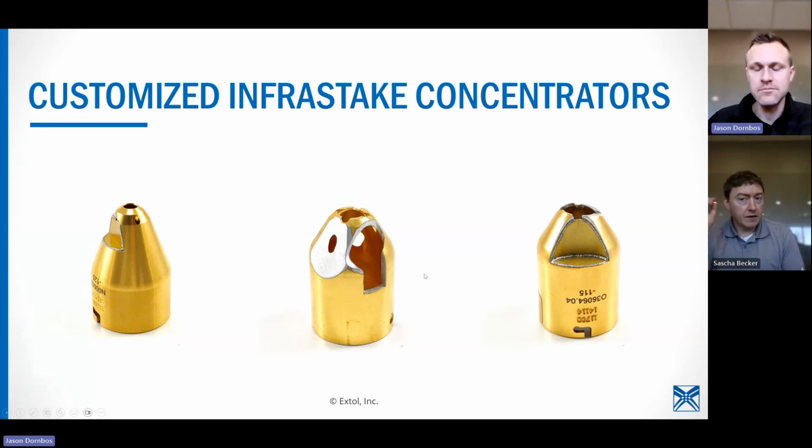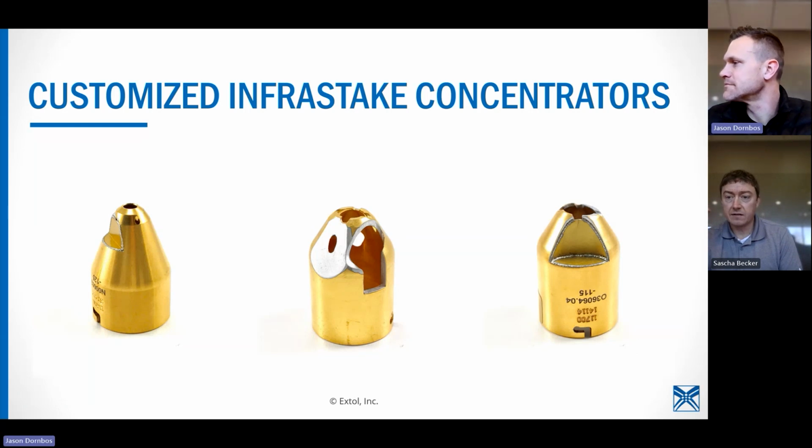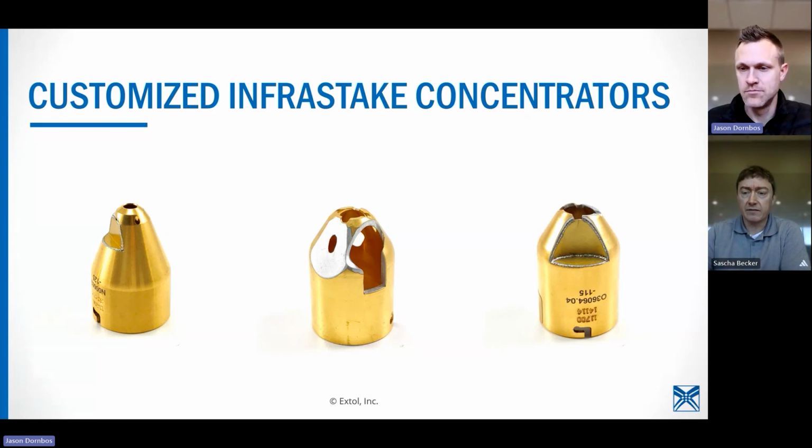Well, I wanted to come back around to Kevin's question. He said that the angle of the concentrator seems to change from job to job, even though the bosses are basically same size, same design. Typically, if we see an angled concentrator or angled module, that's to avoid some other interference, some other part feature. That may be the case for you. If it's not, we'd love to talk more offline and dive a little bit deeper into what you're seeing.